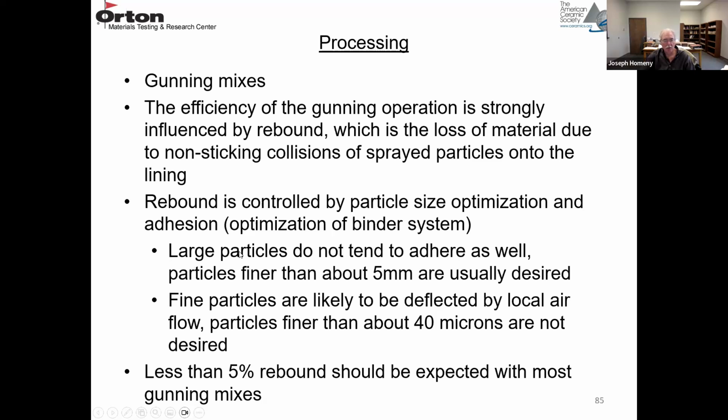Larger particles tend to bounce off the wall or the ceiling, whatever you're gunning. So large particles do not tend to adhere as well. The maximum particle size in a gunning mix is usually 5 millimeters. Bigger particles tend to rebound. Fine particles are deflected by the airstream, and they're not attached to the wall.